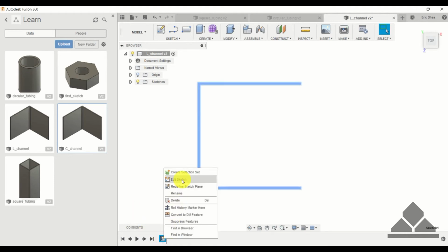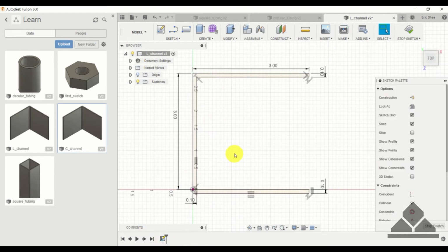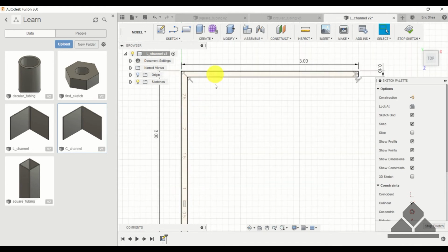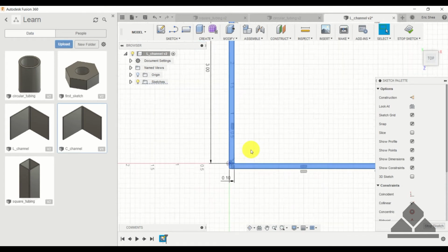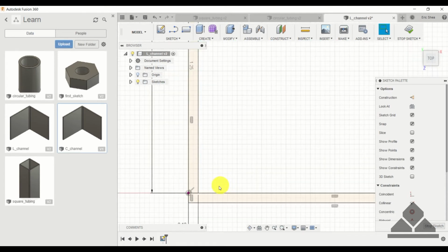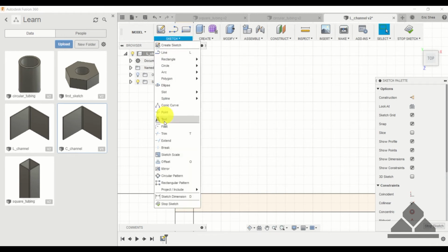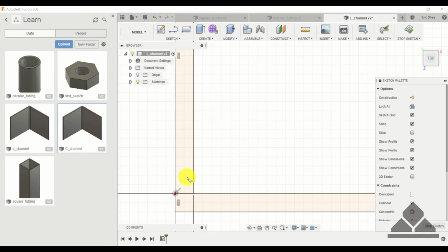So now we have to get back to edit sketch. And since you still have this line here, you would have to click on this sketch, hold down Control, and hit on that sketch. To get rid of that issue, you can use an operation called trim. And you can simply cut out this line.